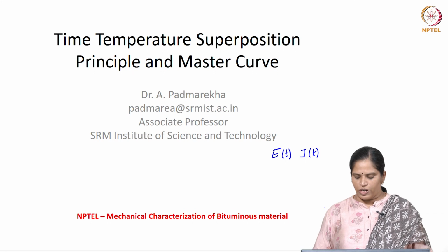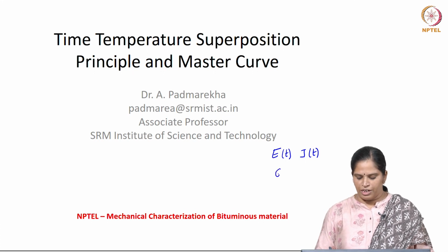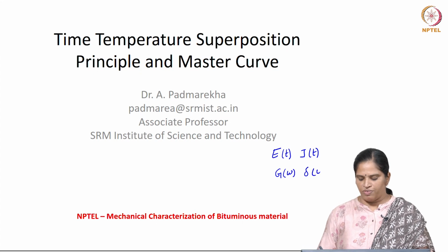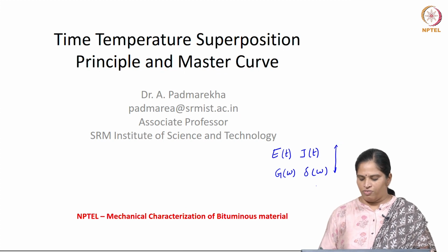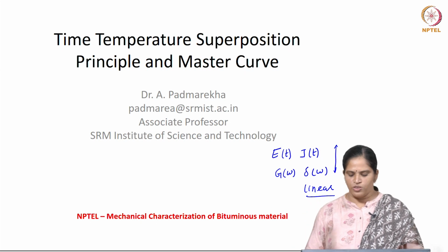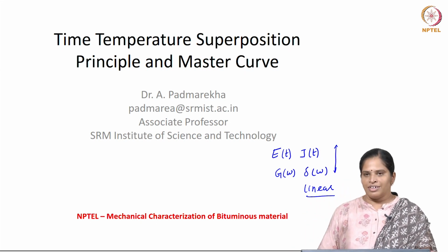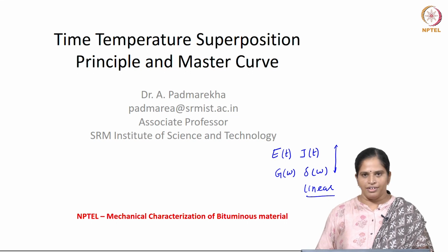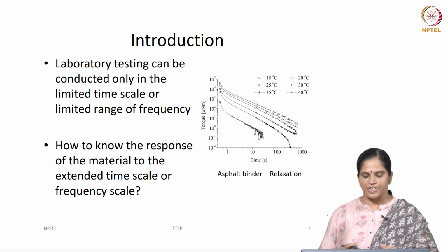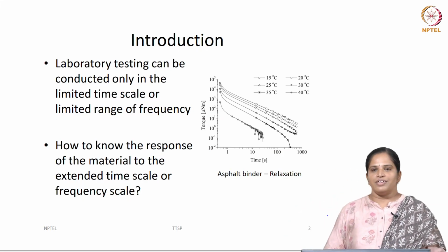You also know in oscillatory mode we use a dynamic modulus function and a phase angle function to characterize the material behavior, and these functions are frequency dependent. So, these functions are valid only if you test the material in the linear regime. So, as of now we are clear about these functions. Now, the next is in the laboratory when you test the material, we have time constraints. So, the testing time or a testing frequency is limited here.